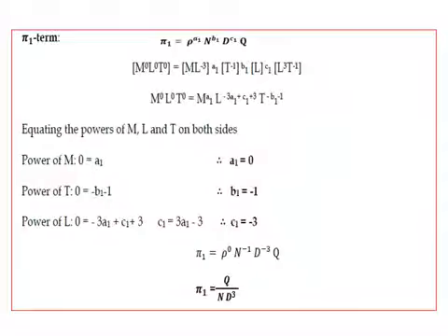Now, in the similar procedure, writing for the pi 1 term: rho you know is ML to the minus 3, n is nothing but rotations per minute, so T to the minus 1, d is L, and discharge is meter cube per second. So it is M to the power of a1, so there is no other M term.